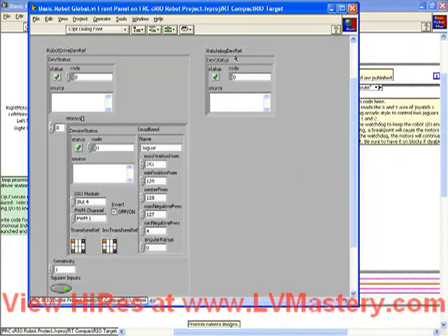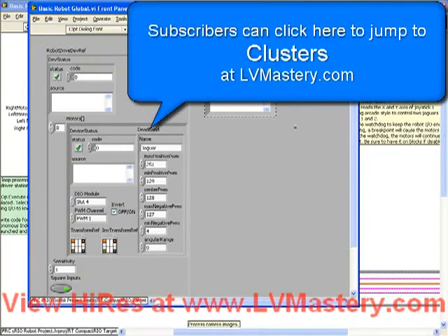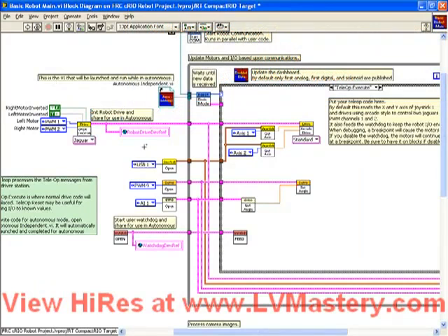And you see what we have here. We have one cluster called Watchdog dev.ref and one called Robot Drive dev.ref. If we go back to this global variable, if we click on it in the center so that we get our finger tool, we can pull that down and select from any of the clusters which have been created on that global variable. What we want to do is add a new element to that global, and the element we want to add is the servo ref.